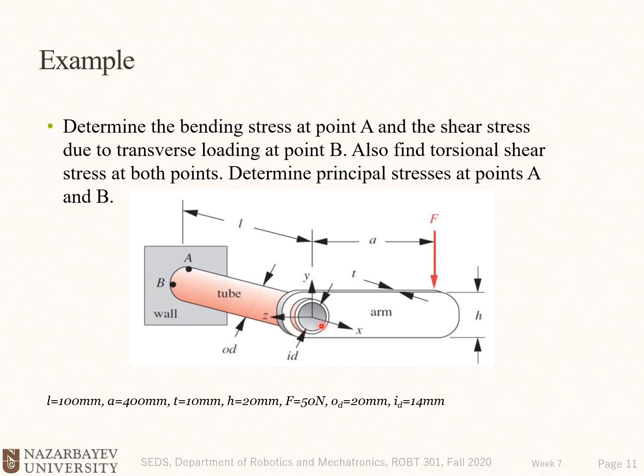For other examples, we need to do bending moment and shear force analysis across the beam and see which cross section is the most critical in terms of maximum bending moment. But this one is a cantilever beam, and it is quite obvious that the base cross section is the critical one. Okay, so we have geometrical parameters here and the force, and we will use these numbers for our calculations.